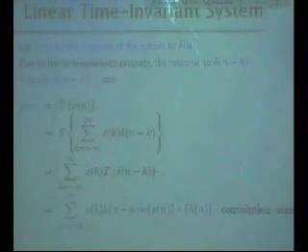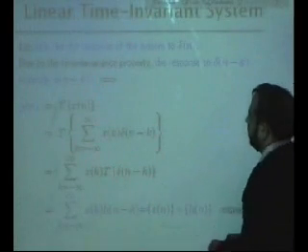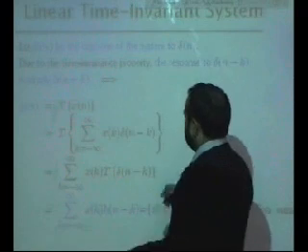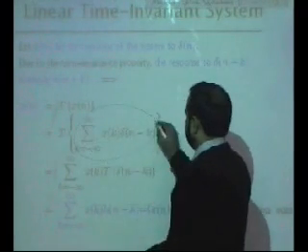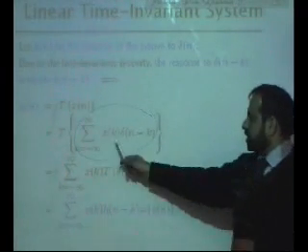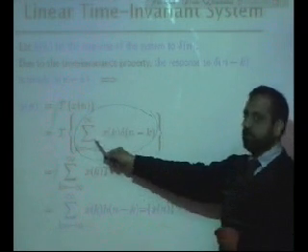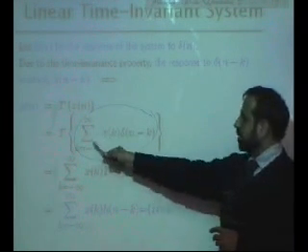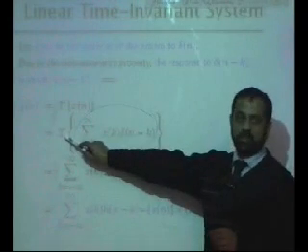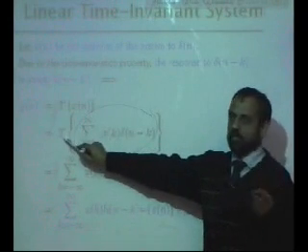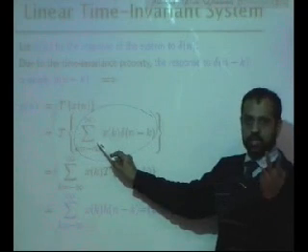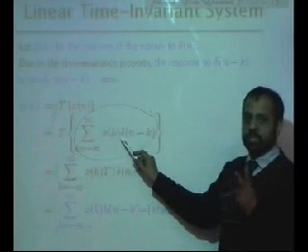I have already concluded this expression, this is another way of just looking at it. This is a general signal, weighted shifted impulses, and you apply a transformation which is linear. Linear means you need not worry about addition, you need not worry about scaling.